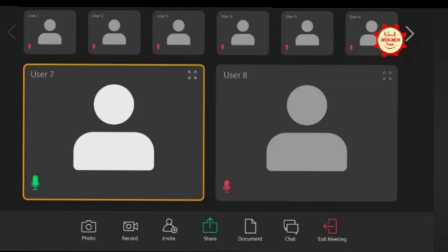The location of guide supports on the column is decided by static engineers depending on piping and with discussion. Where nothing is near the CG, normally we will provide that one, and this will be analyzed by the structure person, whether it will be suitable at that place and what size is to be considered for that one. Correct, Ramakrishna? Yeah, correct. Let me share that.